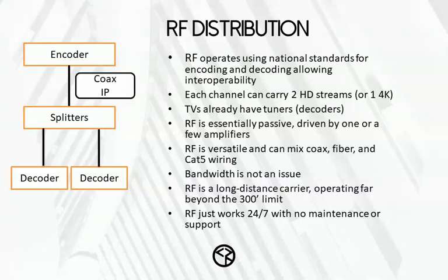However, there are ways that you can also use that same channel to carry a 4K stream, because the encoders, modulators don't care what kind of stream, MPEG-2, MPEG-4, HEVC. It simply puts that stream onto the channel and shoots that out there. So once you have a 4K stream, most modern TVs that you get this year from Samsung and LG and others already have codecs inside for HEVC.